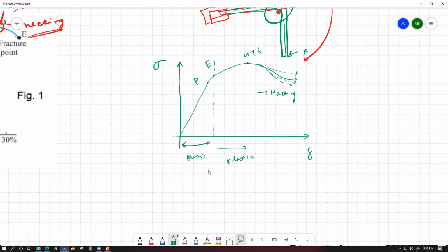Now here's the catch. The highest point on the stress strain graph is what we call the UTS point, or the ultimate tensile stress. This is the maximum amount of stress that specimen can withstand. Beyond this point, what we have started on the specimen is called necking, and from this point, the object can have multiple different breaking behavior. So you can see over here, I've drawn one straight line, multiple different dotted lines, because the object can follow different paths from this point onwards, even though they are all taken from the same sample.